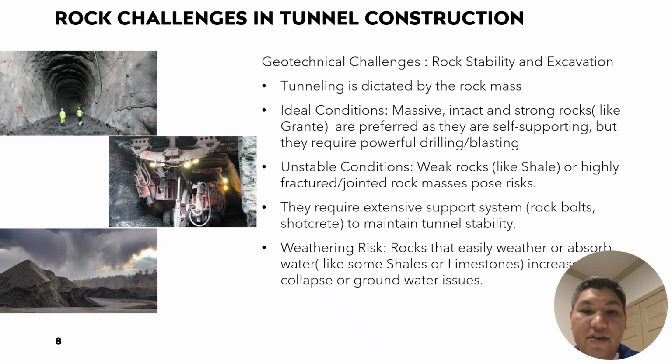In unstable conditions, weak rocks like shale are highly fractured and jointed, posing massive risks. They require extensive support systems like rock bolts and shotcrete to maintain tunnel stability. Weathering risk: rocks easily weather or absorb water, like some shales. Limestone increases cavities and groundwater issues.